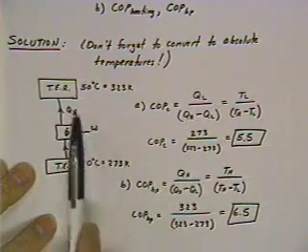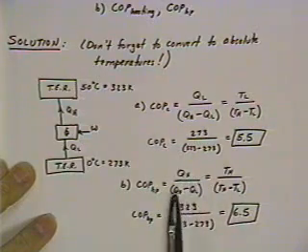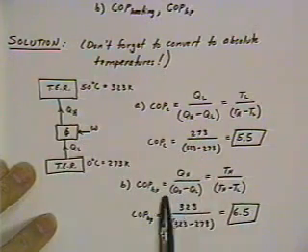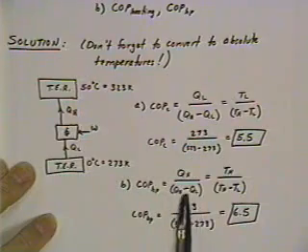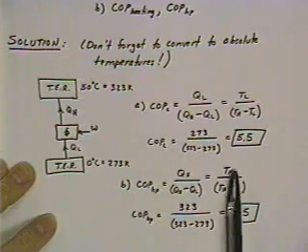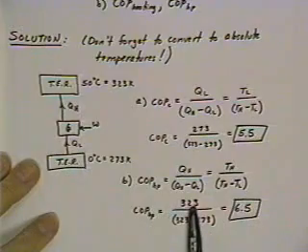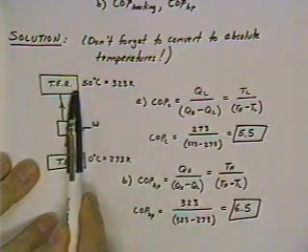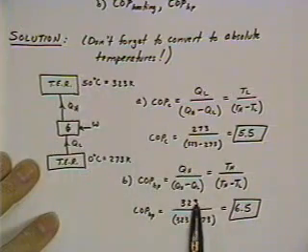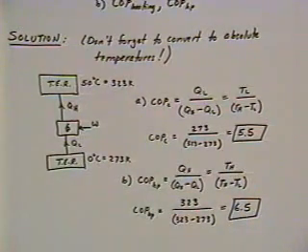This is operating as a heat pump where you're interested in providing heat into the system. And so this is QH over QH minus QL. QH minus QL is the work, or the energy that costs, and this can be converted into absolute temperatures by TH over TH minus TL. And so for heating, you're interested in the high temperature reservoir, it's 323, and so you got 323 minus 273, so you get a COP of 6.5.